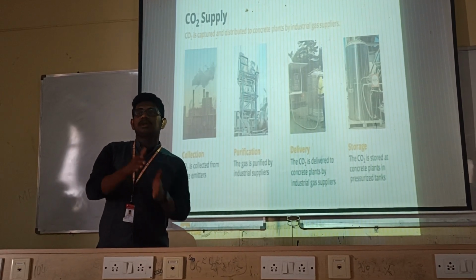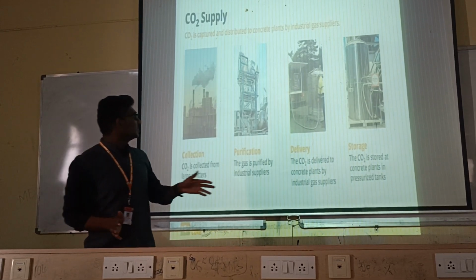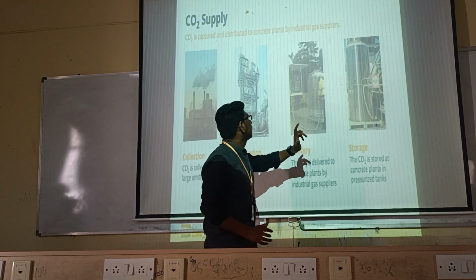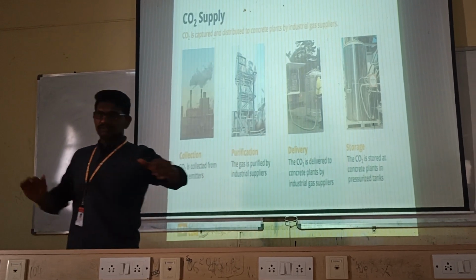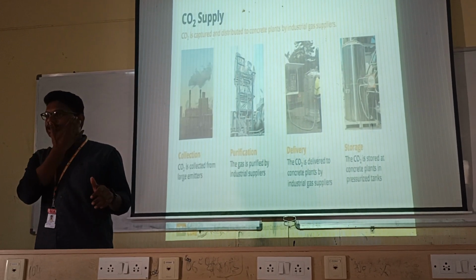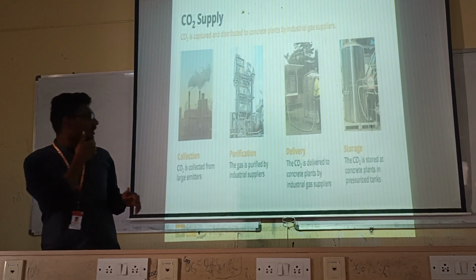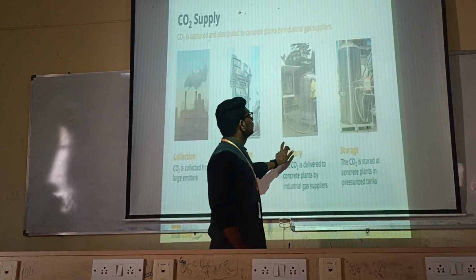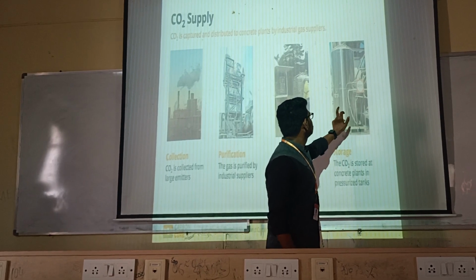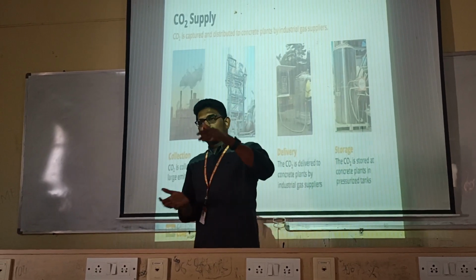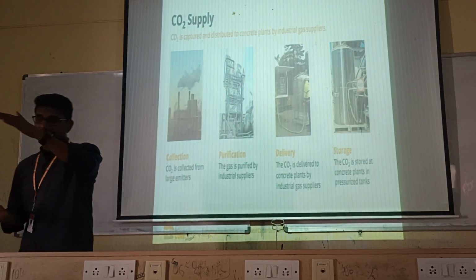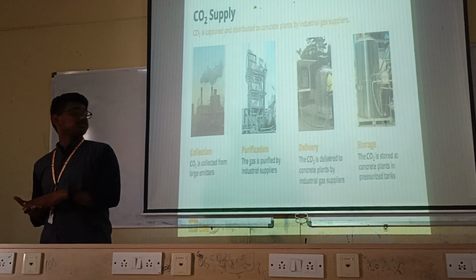The carbon dioxide will be converted into the liquid form, and then it will be delivered to the concrete plants where the CCT technology, I mean the carbon cure technology, is being used. That will be delivered there, and it will be stored in storage tanks. The carbon dioxide will be pressurized and it will be in the liquid form.